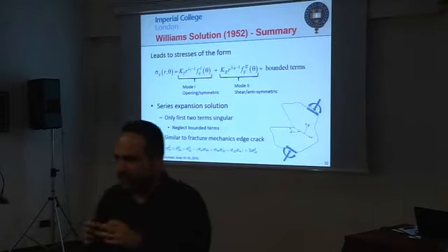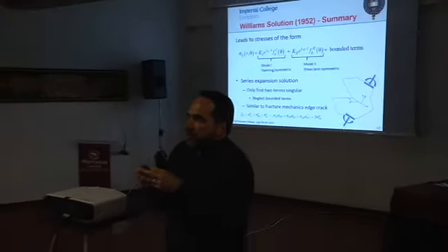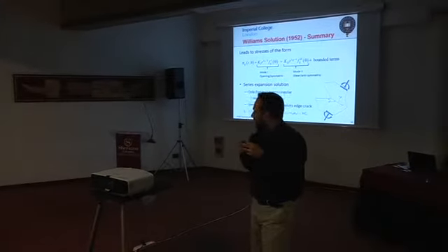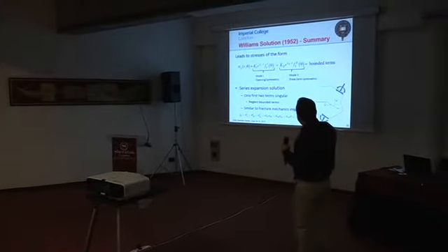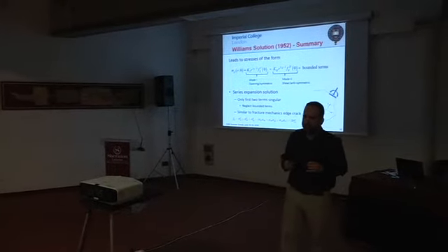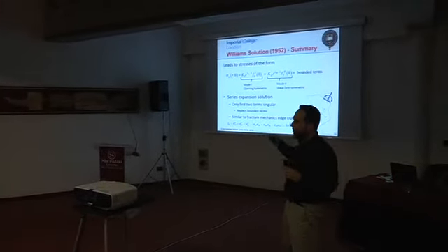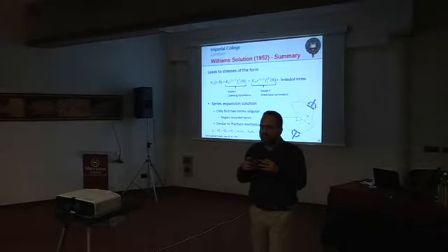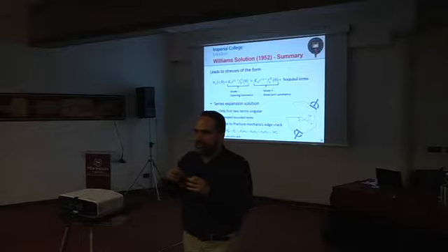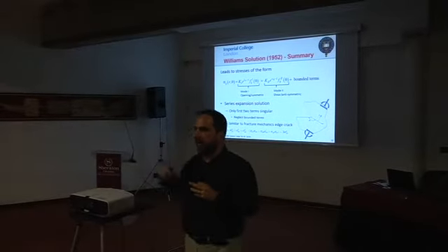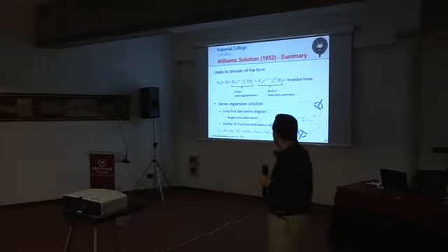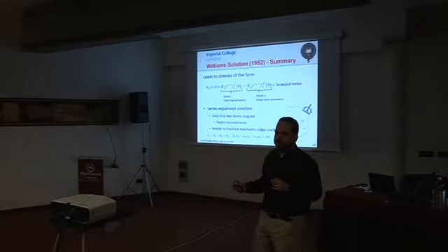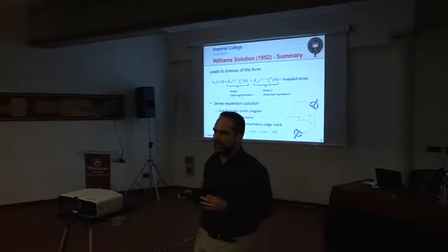So this is a very good description of the stress field very close to the tip. There will be other terms, but we're not considering them yet. And these terms become more and more important as the other dimensions around the notch come into play. So if you have a notch which is very big compared to other dimensions, the bounded terms might become very important because they are felt by the notch very soon.